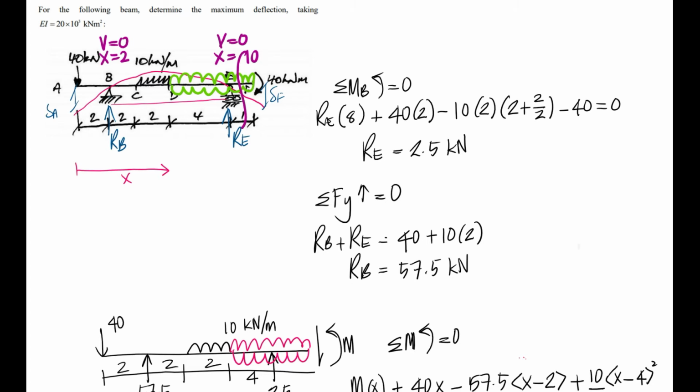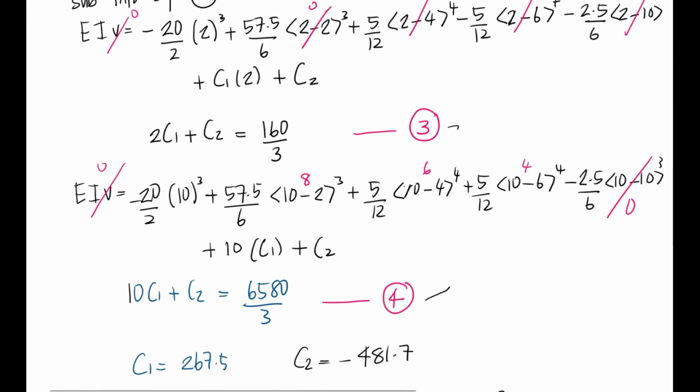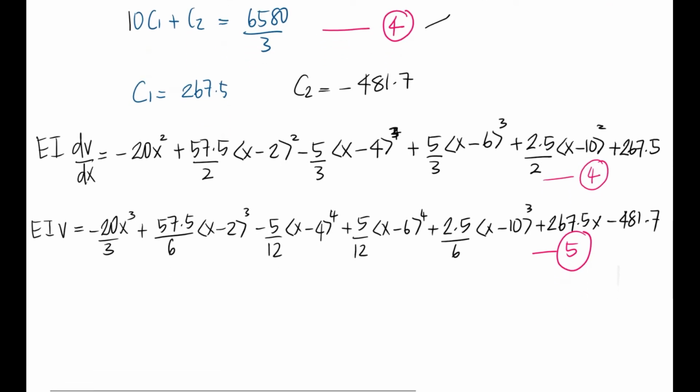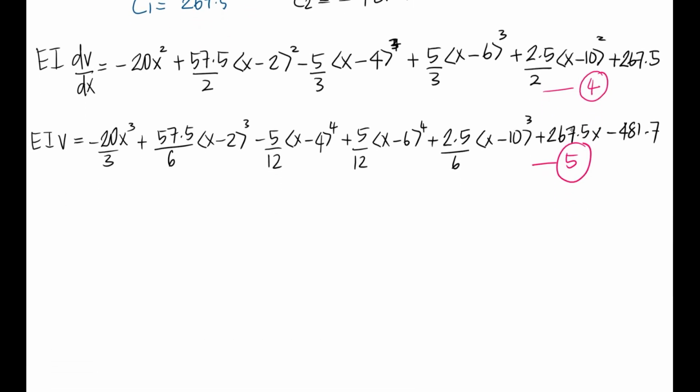Okay, so we solve by using the equation of deflection. As you can see in this equation, we cannot solve algebraically for x. So we need to use trial and error. From the elastic curve, for the maximum deflection we initially choose the midspan where x equal to 6.